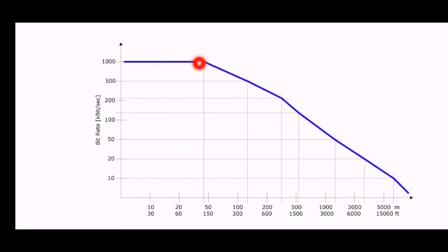You can use more than 40 meters of length, but the bit rate will keep decreasing the farther you go. For example, at 100 meters your transmission rate will be around 500 kbps. It's simple, 1024 kbps is 1 Mbps, so we can consider here it is 1 Mbps and here half a Mbps, or 500 kbps. And it will keep on decreasing.